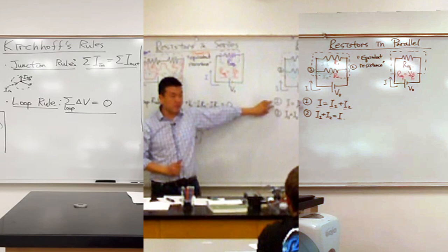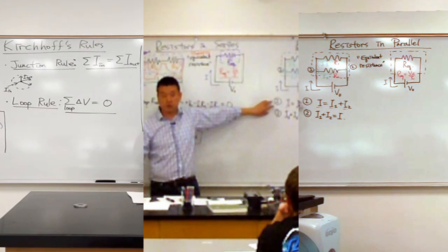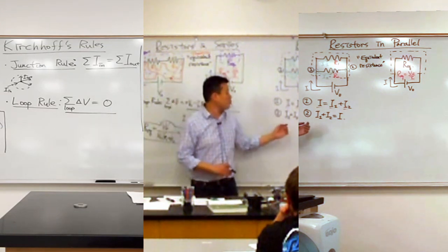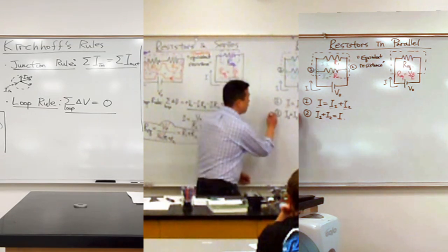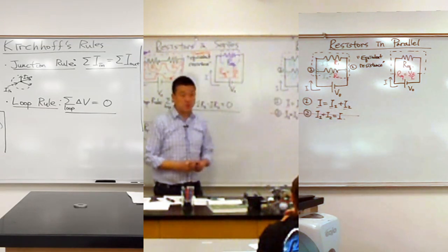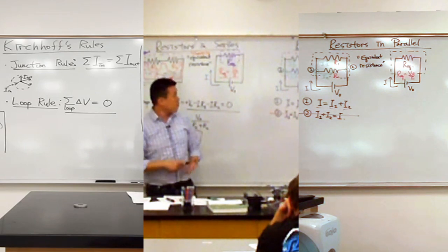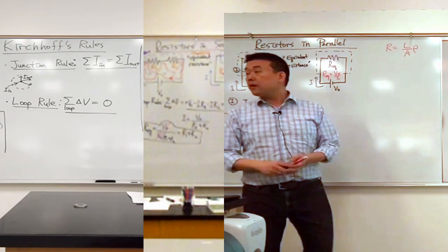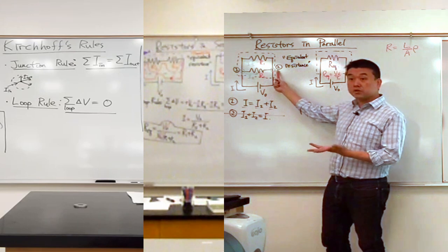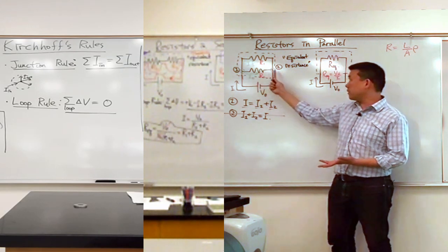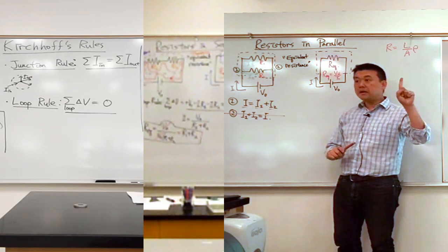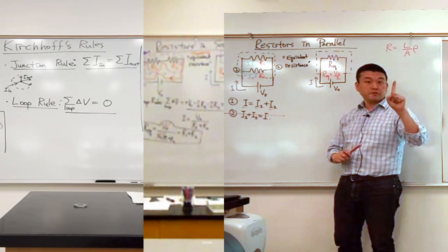Meaning solving a dependent system of equations gets way more complicated than solving an independent system of equations. So the advice I'm giving you in circuit solving, that's also in the handout, is geared towards avoiding dependency. So I'm going to do what I need to do to avoid introducing the second equation, which doesn't actually add anything. So this is the advice that I give you in the handout. When you see the number of junctions in your circuit, the number of times you should use the junction rule is the total number minus 1. Leave 1 junction unused. So that's what you see here.